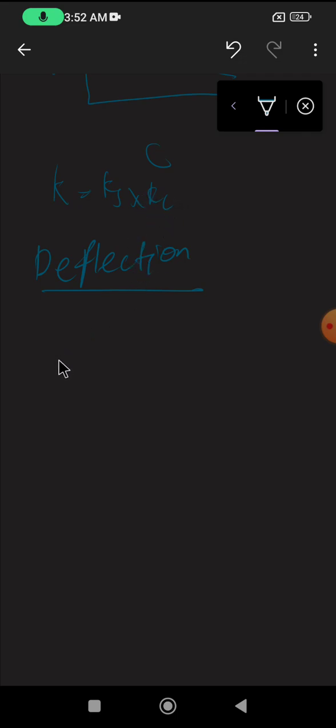The total active length of the wire L is equal to the length of one coil, pi D, into the number of coils n. Theta is the angular deflection of the wire when acted upon by the torque T. This is angular, not linear.